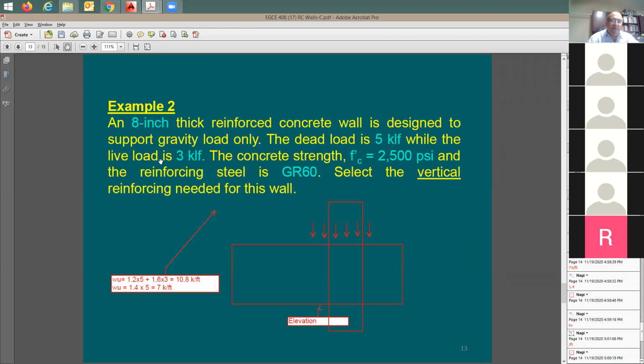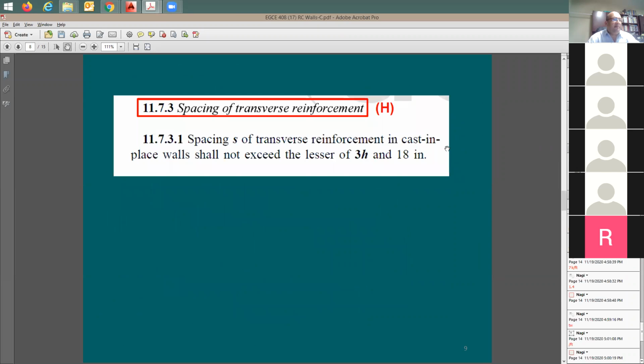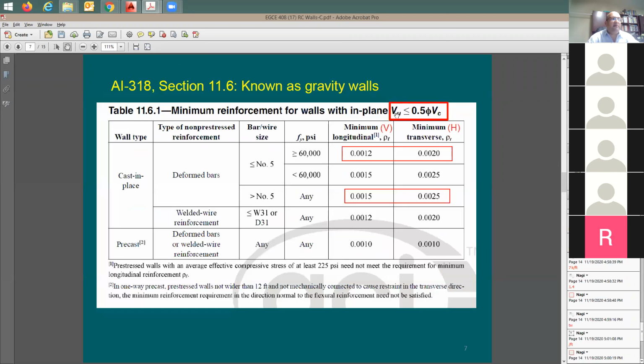Did you see any shear forces? No. So in this case, what's the conclusion? The conclusion is simple: I don't have shear demand. So it is true that V sub U is going to be less than 0.5 phi V sub c. So I'm going to say yes, this table is the table I can use in my analysis.